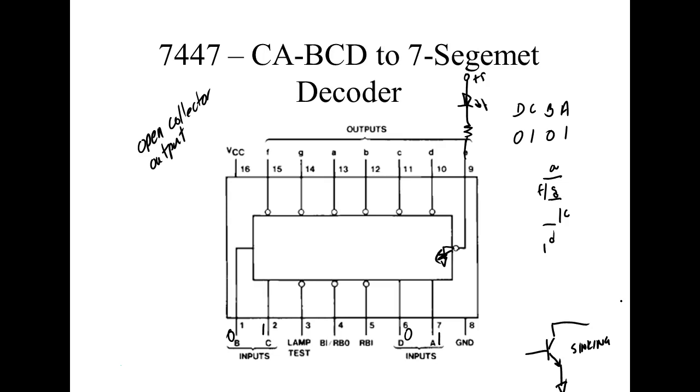One of our instructors was teaching the class, and they wired up, and she said, this 7442 is not doing what it's supposed to be. She had a 7447 for one thing. And she wasn't getting true highs out of it because she was using it as a 7442, right? You understand? She wasn't getting true highs out, and it was doing crazy things. And I said, well, you're using a 7447. That's a 7-segment display, common anode. So the anodes, we call it a common anode.